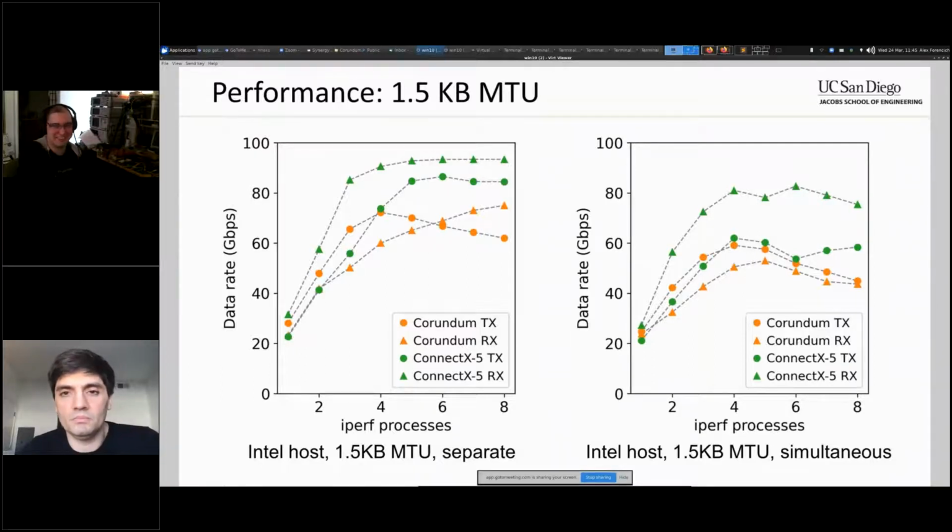So, got it. But yeah, I have not done any testing at that level, because even just moving that data over PCI Express is a problem. There's too much PCI Express overhead. If you're reading each packet in a separate DMA operation, it's impossible to get 100 gigabits per second over a Gen 3 x16 link.